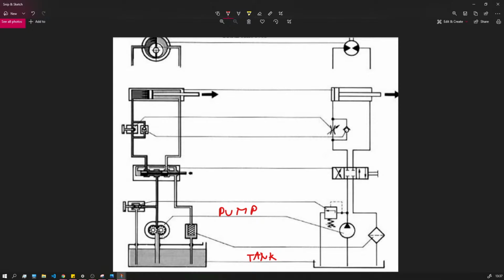The pump generates the kinetic energy. The kinetic energy is converted into potential energy in the system by plugging the line. That's the most dramatic resistance. That's basically like driving straight through a wall, trying to go through a wall, basically. And that means that the kinetic energy transferred from the pump stops there and converts to potential energy, and we have the most pressure in this case.